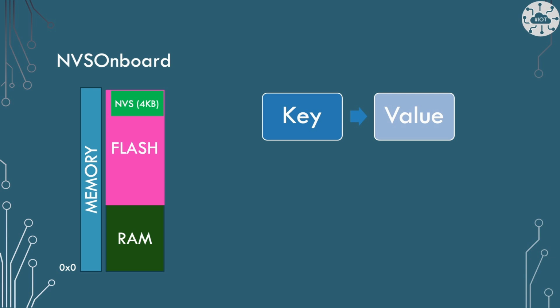I was thinking when I was writing this that, well, those keys are going to take up a lot of space because they're all strings, by default up to 16 characters length. But to be honest, we've got 4K. We've got loads of space. Considering what I'm really going to store there, which is probably going to be Wi-Fi access keys or at most SSL certificates, it's actually not going to be very full.